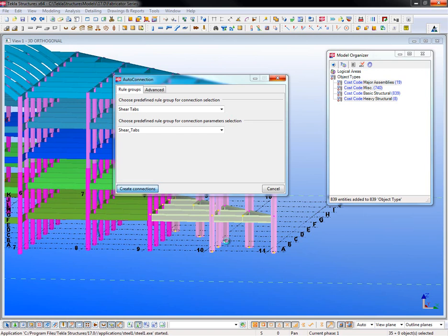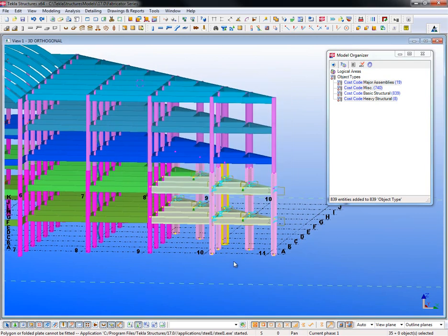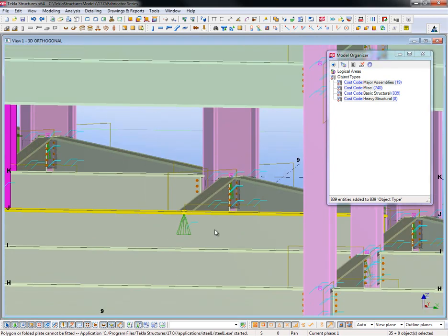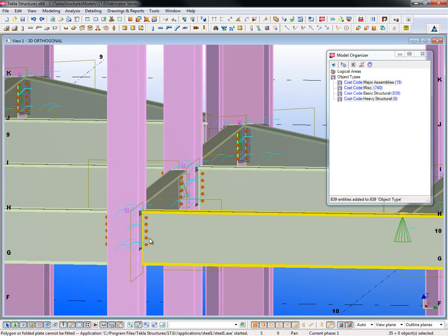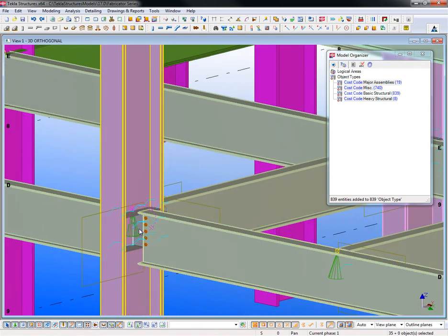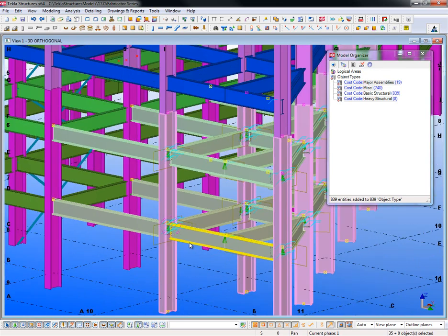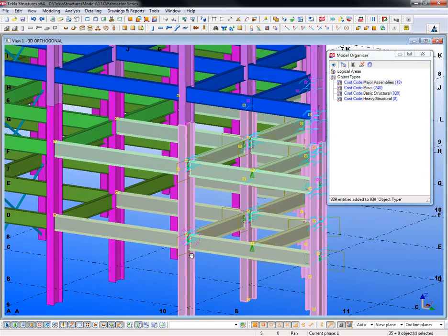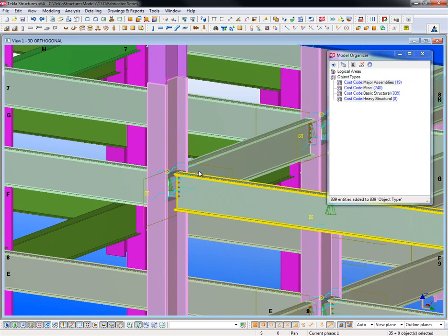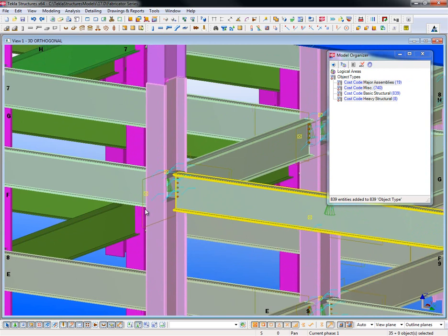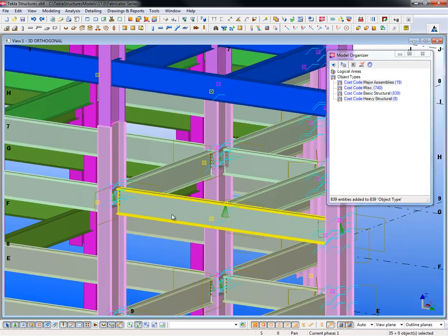This is a system that we've developed, or that we've localized here, for our Tekla users. But of course, if you had your own auto connection system, you could develop that yourself. It's basically just a set of rules that defines what you want to do where one piece of steel hits another piece of steel. Yeah, exactly. You're just defining rules that if I have a beam going into a column and it's a perpendicular situation, use this connection. If it's skewed, use this connection, or whatever. It just runs through the different rules.